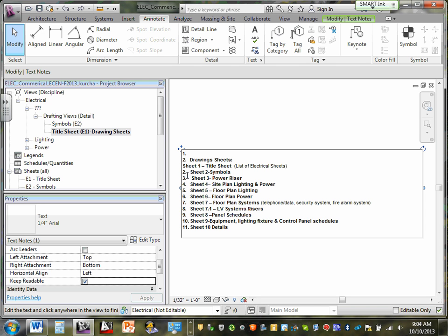So I would like you guys to sheet. Is that how we did it this last time? I would like you to type E next to them, please. So start with the first one, E1, and how did we do that? E1, and space, and then instead of sheet, E1 and then title sheet. That's how it's going to look. And you can edit them, get rid of this. The only thing you need is symbol sheet here, right? And then the same thing, and then you do the rest. You come over here, and then that will be E2 and so forth.